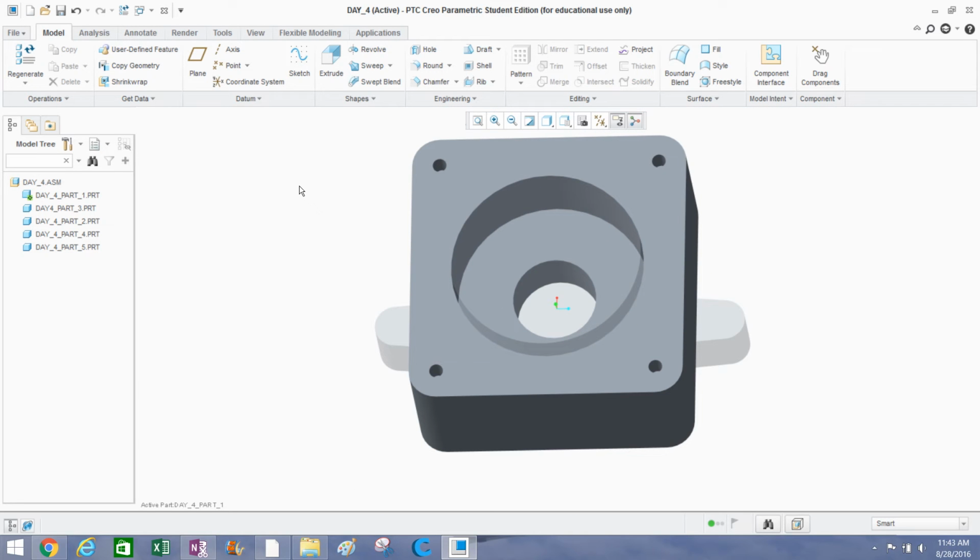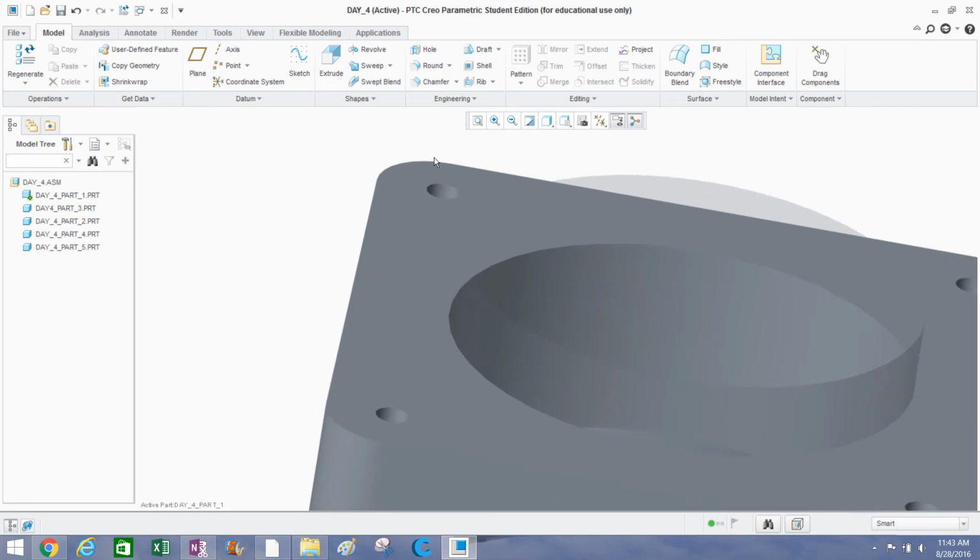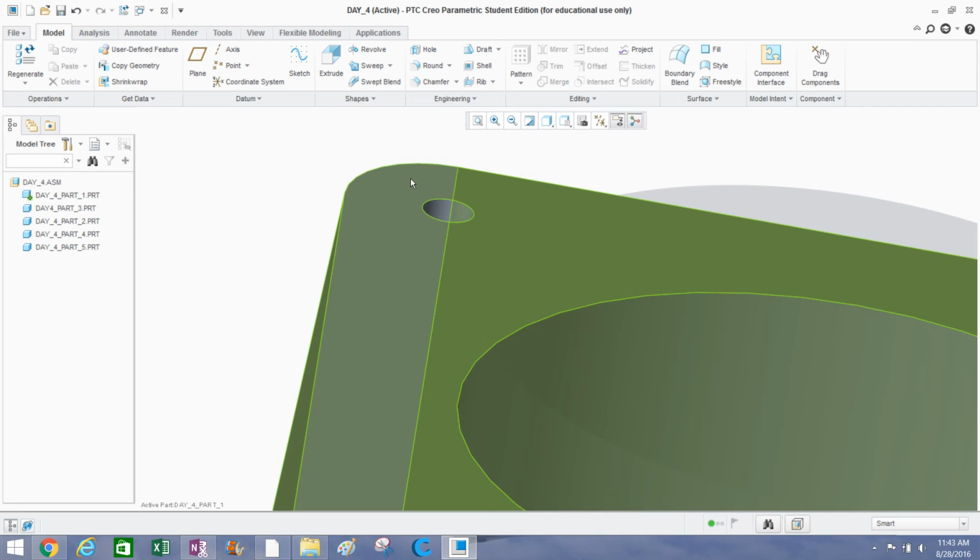We're going to go ahead now and put a counterbore hole in this. The use of this would be if you were, let's say, installing a screw into this part, and you want the screw head to be flush with the bottom of the part here. Obviously, the screw head at this point would be sitting on this flat surface and sticking out, and a 1/2 inch screw, that could be about a 1/2 inch that it would be sticking out here.